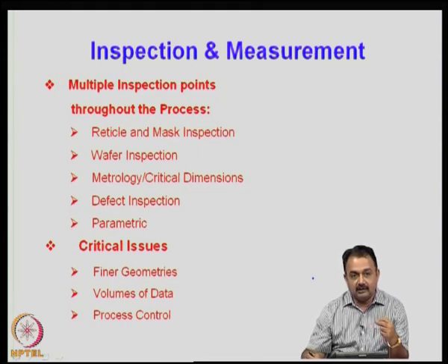I want to emphasize here the inspection, measurement and quality control at every stage. The steps that we have mentioned may not be exactly the same, because there may be very many intermediate steps, including rinsing, other methods of cleaning, and inspection and so on. So, it takes a while from the silicon wafer to a single die to be complete. At each step, the quality control personnel will have to look for various defects and certify it.